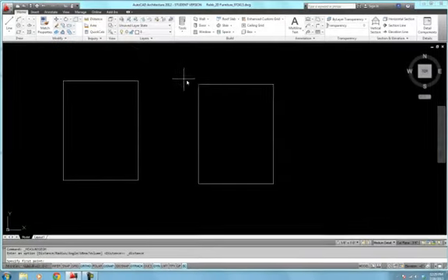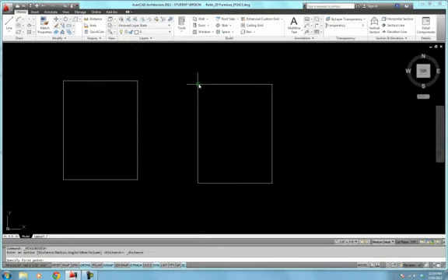And the way the distance tool works is AutoCAD wants you to specify 2 points on the screen, 1, 2, and it will tell you what the distance between those 2 points is. So that horizontal line segment from endpoint to endpoint, which is why we need to have the O-snaps on, is defined as 5 feet 0 inches long.